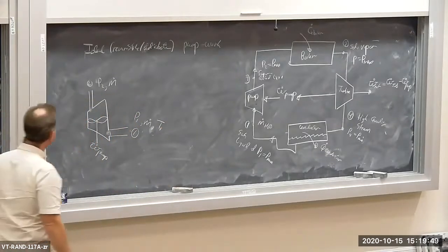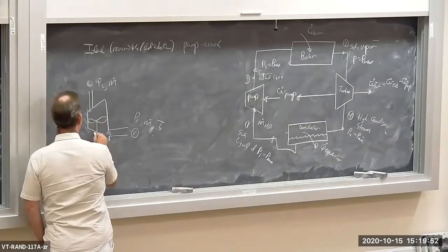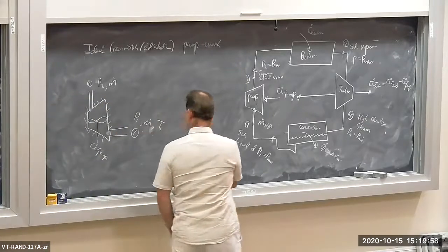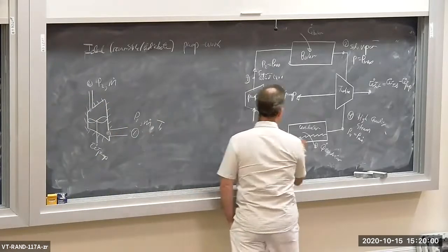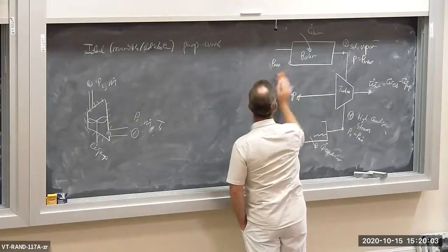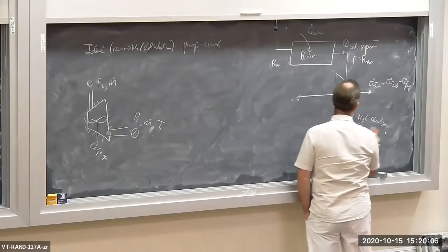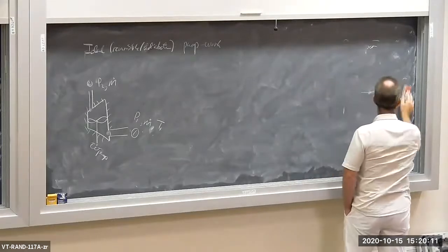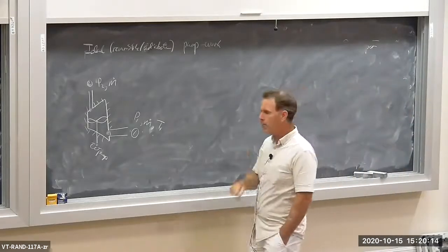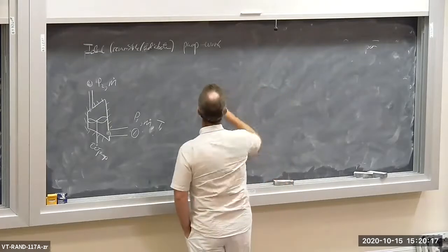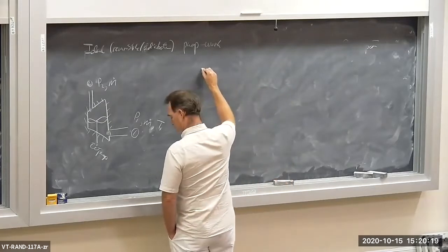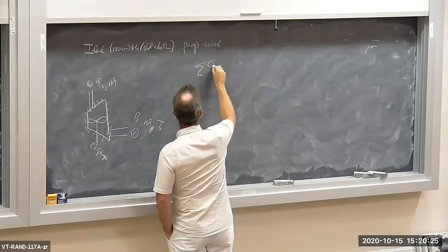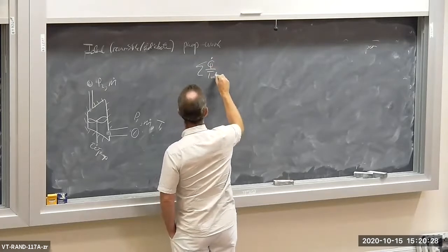Now, this thing is reversible and adiabatic. So, it's insulated. Let's apply the entropy balance and see what we get with a reversible adiabatic pump. If your gut intuition is that it's an isentropic pump, you're absolutely right. So here, S balance, we got, so for an open system, we have the sum of Q dot over the interaction temperature.